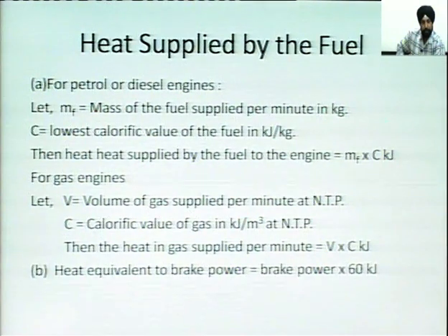And for gas engines, if V is the volume of the gas supplied per minute at normal temperature and pressure, and C is the calorific value of gas, because we know that for liquid fuels the fuel is measured in kg, and for gases it is measured in volume, then the heat supplied to the gas engine per minute will be equal to the product of the volume of the gas consumed by the engine and its calorific value.